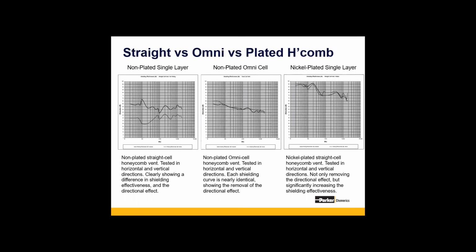So it really becomes an airflow type discussion. Obviously a 60 degree, the most dramatic, is going to give you the most privacy, right? You're going to have to get down into the most of an angle to actually see through the cells. And it's also going to provide the most wicking action at that high angle. But again, it's going to decrease your airflow the most because now you're putting up almost a wall to the airflow. So it really becomes that whole trade-off question between airflow, how much privacy is needed, and how much wicking action you need for moisture.